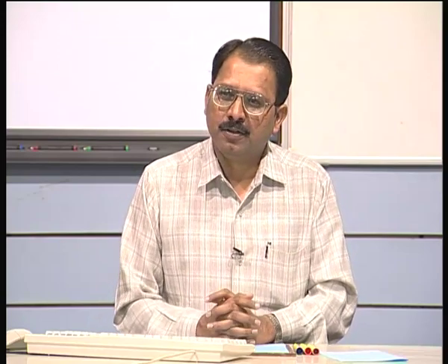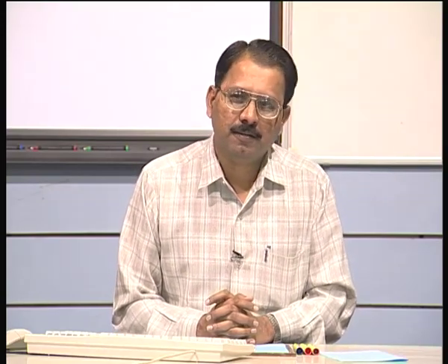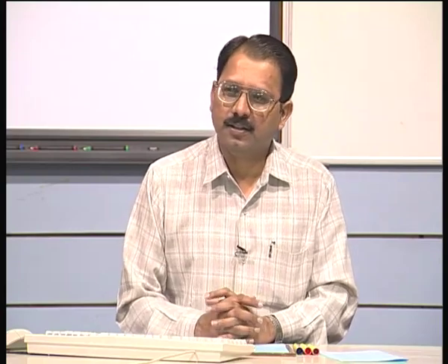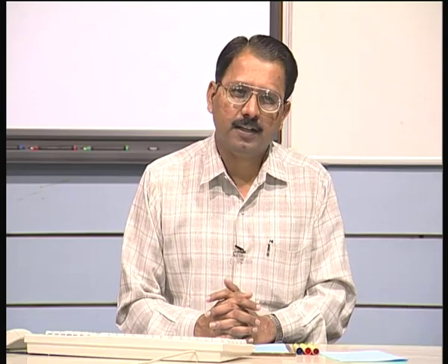We discussed sweep when we were discussing parametric surfaces. Sweeping is a concept which can be applied to curves, surfaces and solids. A point which is swept along a path gives me a curve. If I take a curve or a straight line and sweep it along a certain curved or straight path, then I get a surface.